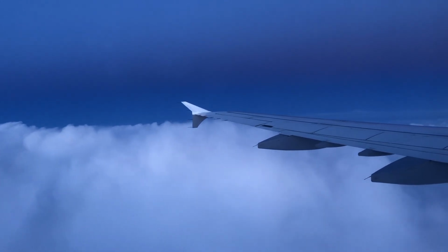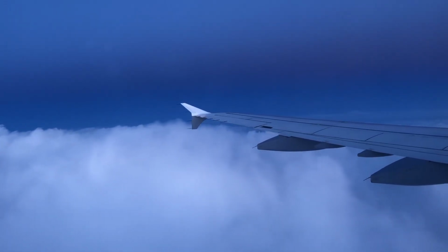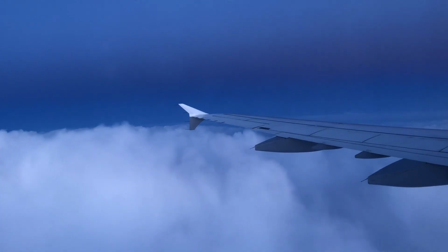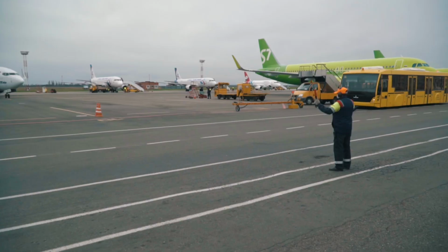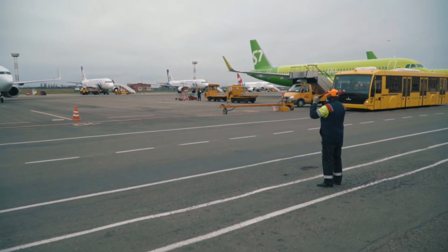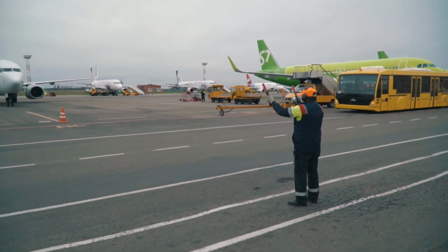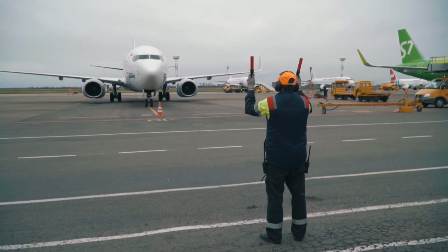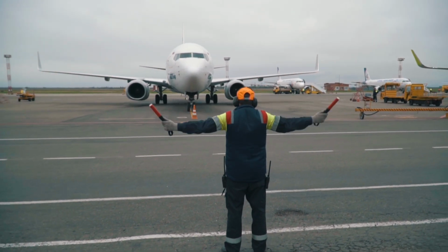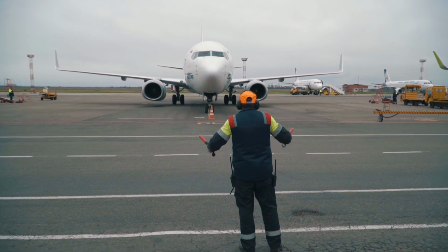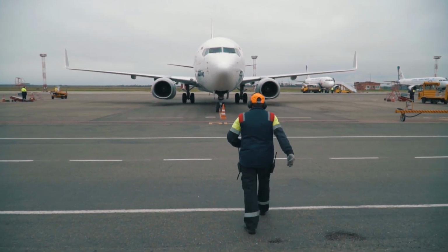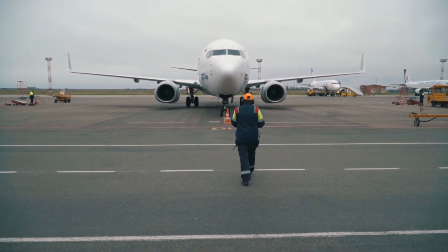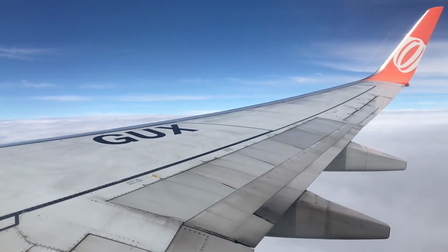But here's the fascinating part. The winglet itself generates lift. However, this lift is angled. Instead of acting purely upward, it tilts slightly forward. That forward component helps counteract induced drag. So the winglet isn't just reducing drag, it's actively producing a force that improves efficiency. This is why winglets are so powerful. They don't just block airflow, they transform it.